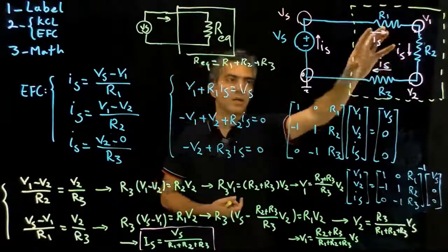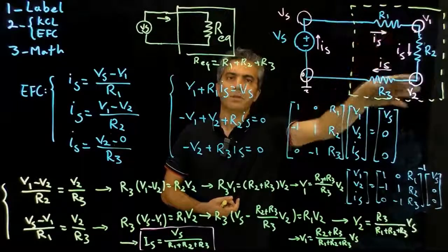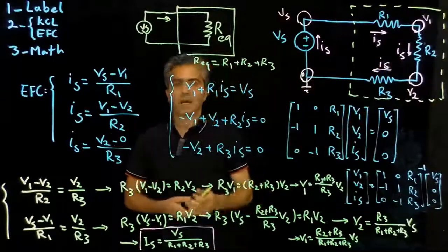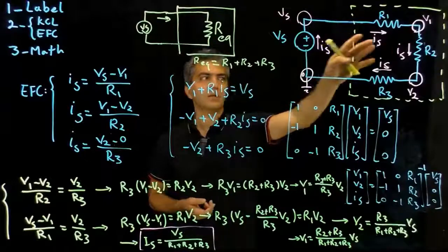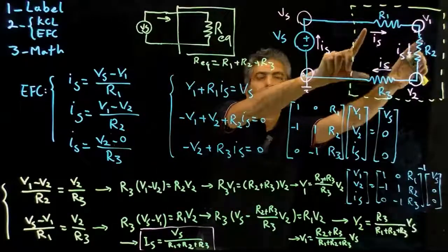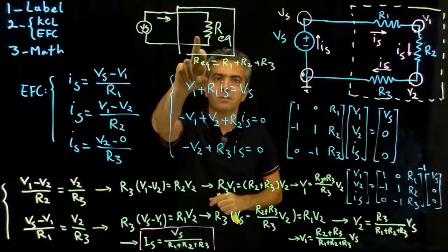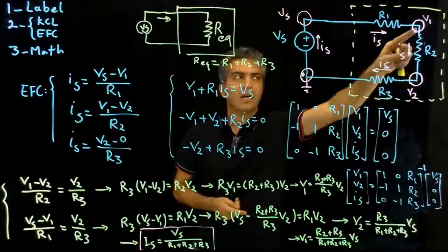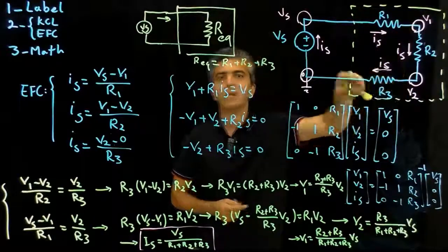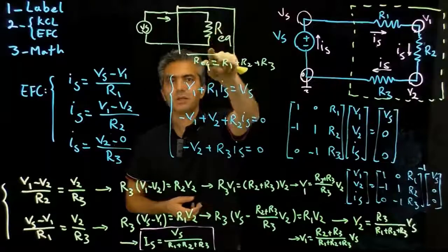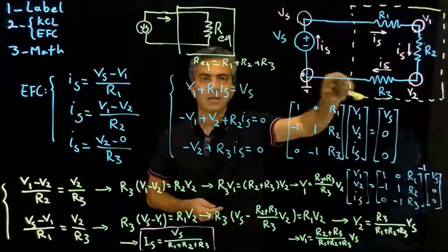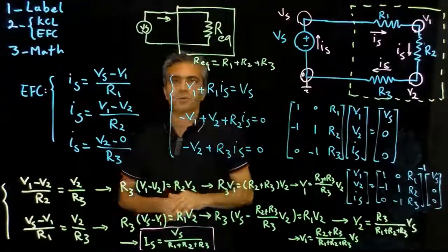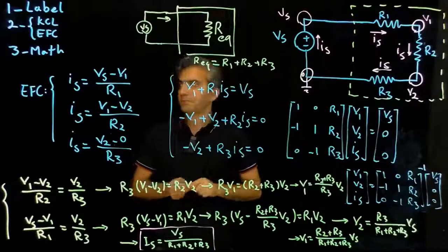So we take components that are in series to each other, take their resistances and add them up and use that as the equivalent to that circuit. Obviously, when you replace that bunch of components with just one resistor, at that point you're losing all the information about the voltages that existed in between each component. They don't exist here, and this technique is only useful if you don't care about that information, and all you need is the current that is going to pass through the whole thing combined.